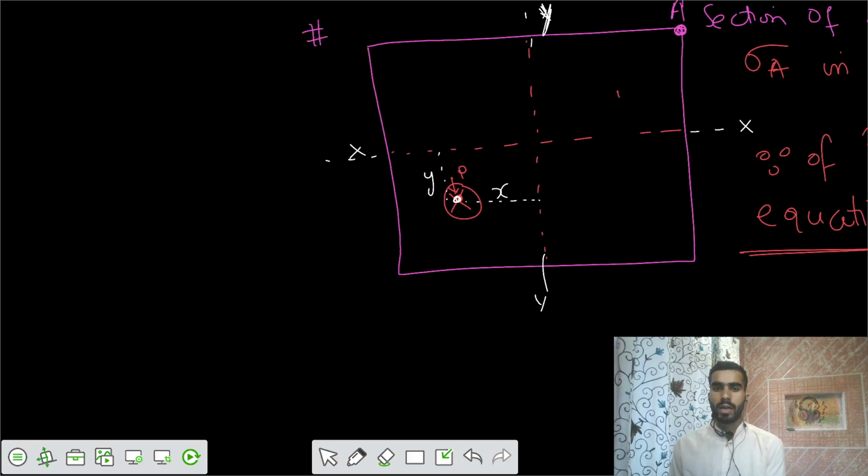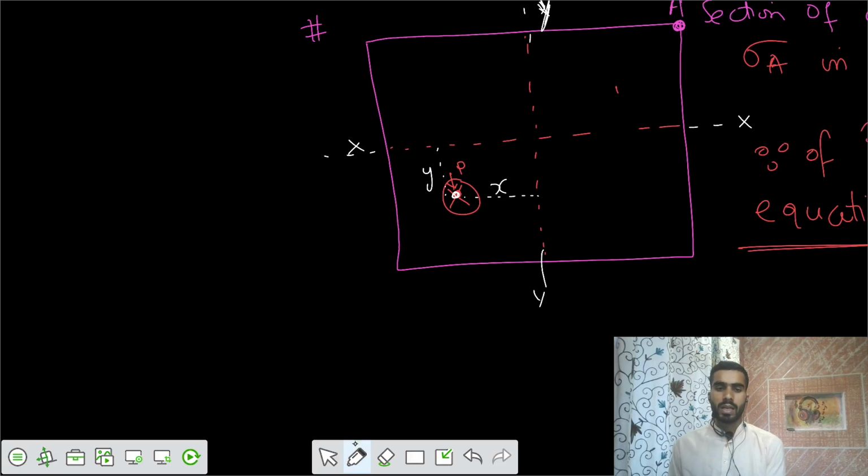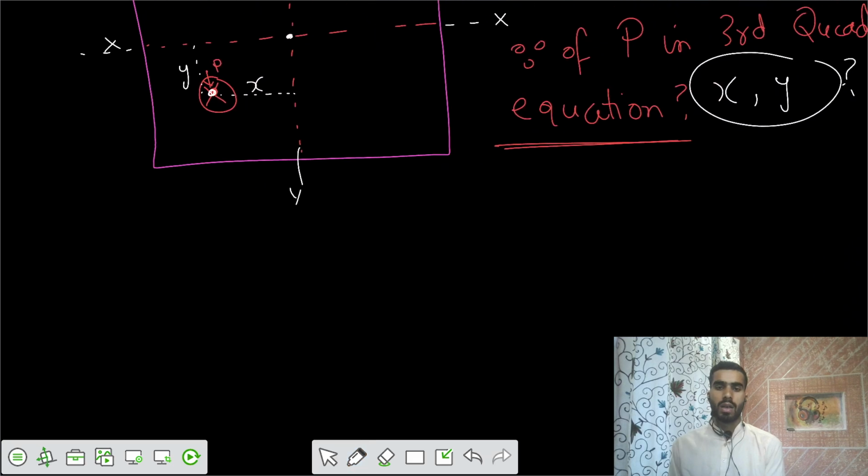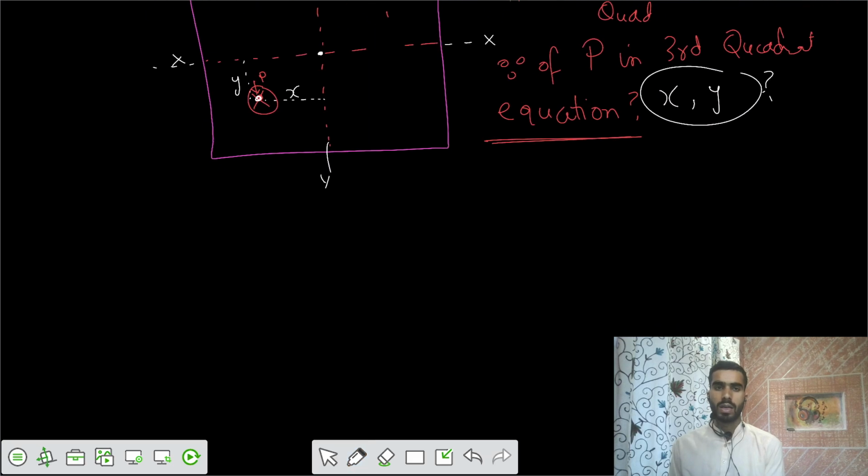Now if I want to do that, you transfer the effect of that force P onto the centroid, and you want to have the effect of moments also about these two axes. Let's say this is your reference x line, and your load is here somewhere. That means a hogging moment has been developed in this fashion: moment of P into y about this axis.